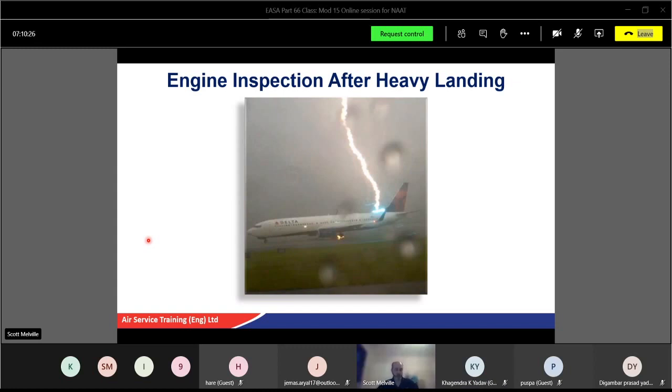Compressor damage can be generally assessed as 3 types of damage. What were they? Superficial, impact, repairable. So superficial, again, a small dent, which is standard normal. Impact damage, as it sounds. Repairable damage, minor grit you can blend out. Tomorrow, we'll look at how we can blend a blade in situ without taking the blade out, providing it's within limits. Good. That's easy. Not giving you easy ones.